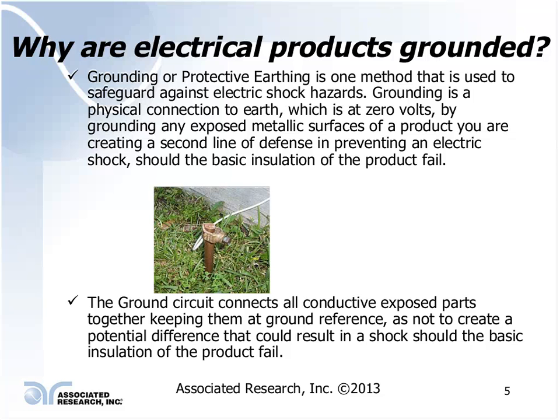It is there to create a second line of defense in guarding against any electrical shock hazard should the insulation within the product itself fail. This ground circuit connects all conductive exposed parts within a product together, keeping them at this ground reference. So you don't have a difference of potential between two products that are sitting next to each other, so that if you could contact one and contact another, that could create a shock hazard